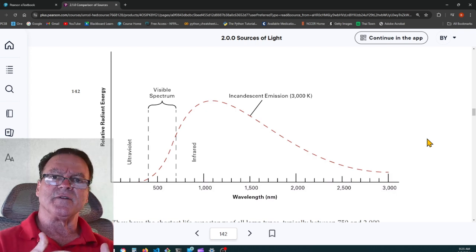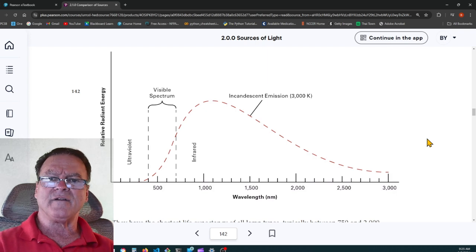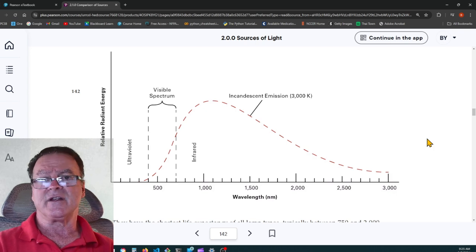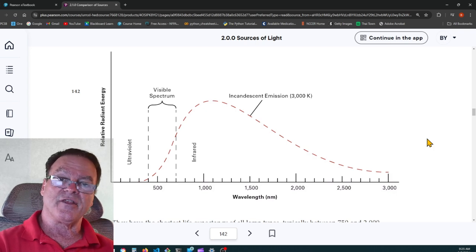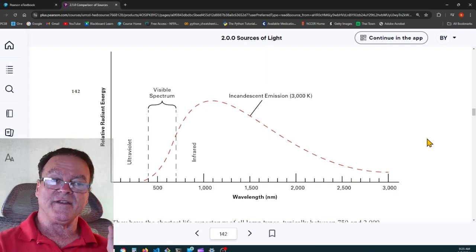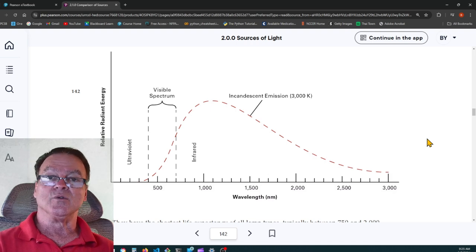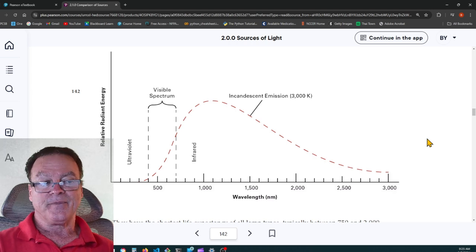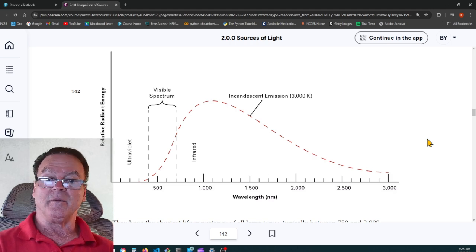When you have a customer and they say, yeah, my light will go off like every 2 minutes. It'll be on for a while, and then it goes out. And then it comes on all by itself, and then it goes out. Well, that's because it's got a thermal protector internally of that light. And when it gets too hot, the thermal protector will open and disconnect the power. And when it cools off to the point that the thermal protector closes, then the light will come back on for another couple of minutes, and then it'll keep going out.